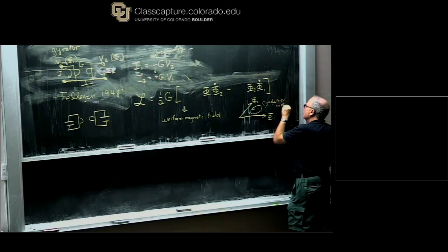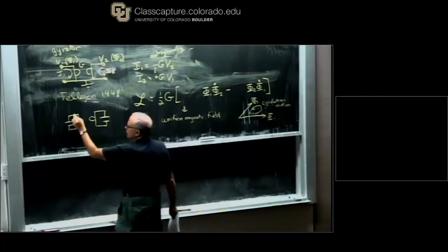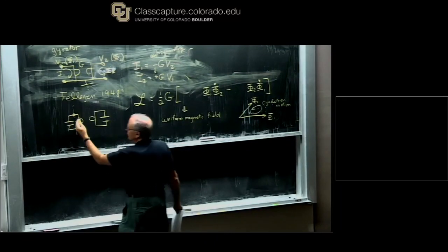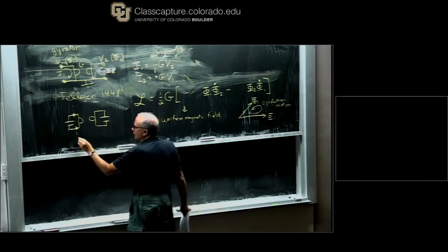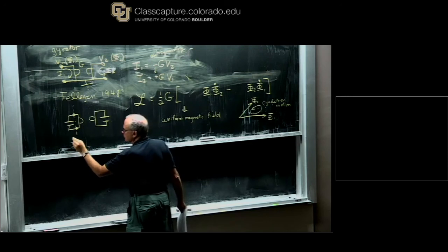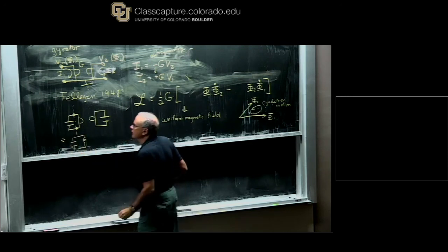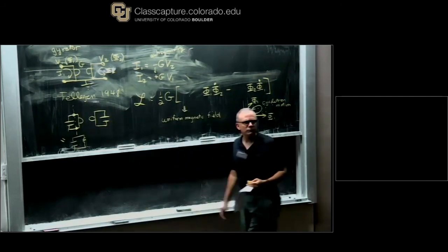So in fact, it is a kind of harmonic oscillator, and that corresponds to one of Tellegen's theorems, which is that if you have a combination like this, a gyrator and a capacitor, it's equivalent to an inductor. So we would say this is a resonant circuit.